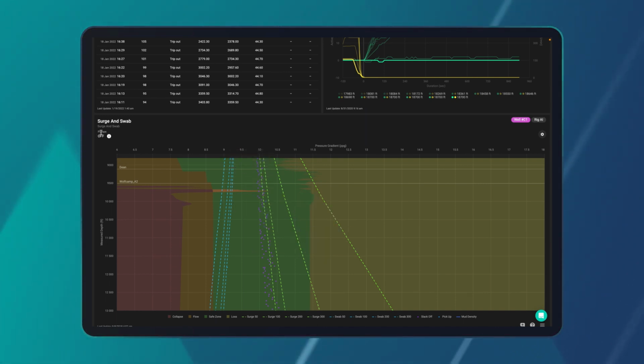It also pulls in your mud pump state, your live mud weights. If you have an MPD system, it'll pull in your MPD back pressure, as well as if you're running through a Coriolis, we can live consume that mud density data as well. So that way, these calculations are very, very tight. And again, really helps to get to section TD to trip in, trip out with the optimal parameters. So this, in conjunction with Tripping Speeds app and with other workflows in Corva, really finds that optimal sweet spot for performance.